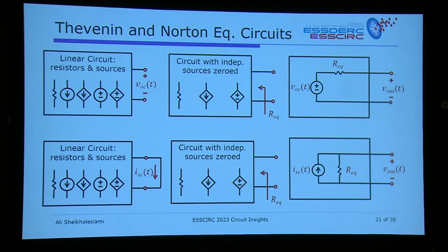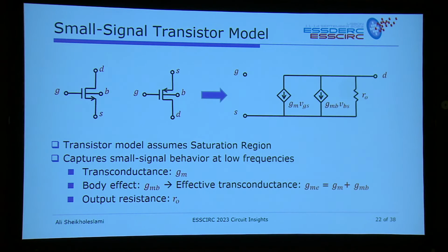Now, when we move up to transistors, the same story applies actually. So if you look at a single NMOS transistor or a PMOS transistor, of course the transistors are nonlinear, but in analog circuit design we are trying to bias them at a point where we're only going to have a small signal perturbation, and in that area it is going to be linear. And you have seen, probably remember if you're an undergrad, that this is the model of a transistor at low frequencies. There are no capacitors shown, just the resistive, low frequency behavior.